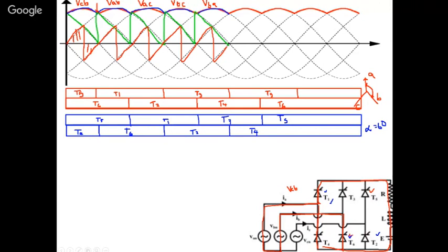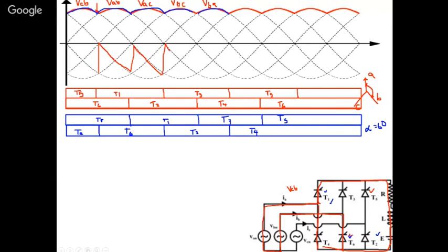Okay. Now you just go for the next. Next is nothing but your 120 degrees. For 120 degrees, you will get a voltage like this. Just opposite to the 60 degrees that was drawn. So you will get a voltage like this. So at 120, what happened? The voltage is negative. Your average voltage became negative.